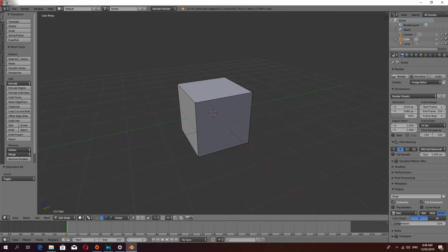To switch between these different selection modes, currently we're in vertex selection mode. So if I right click one of these points, I can select one. To switch between them, down the bottom here, there is the little toolbar which has changed. Notice it's different in object mode than edit mode. Now I can select edges, and then the last one is faces, which lets me select faces.